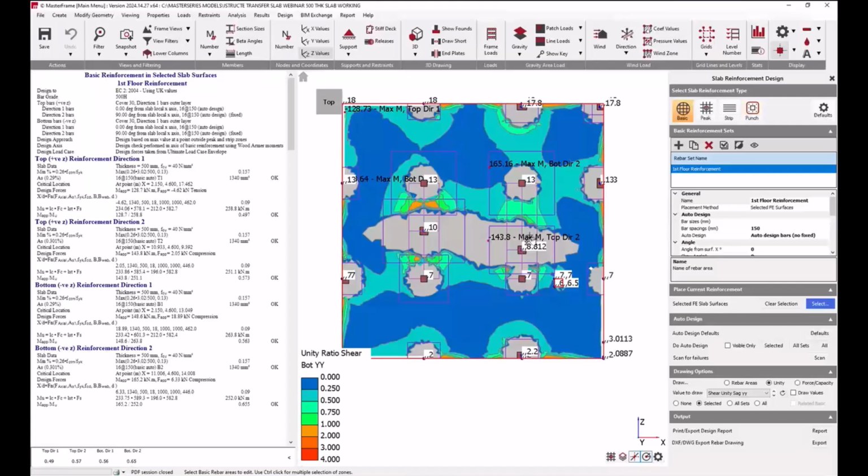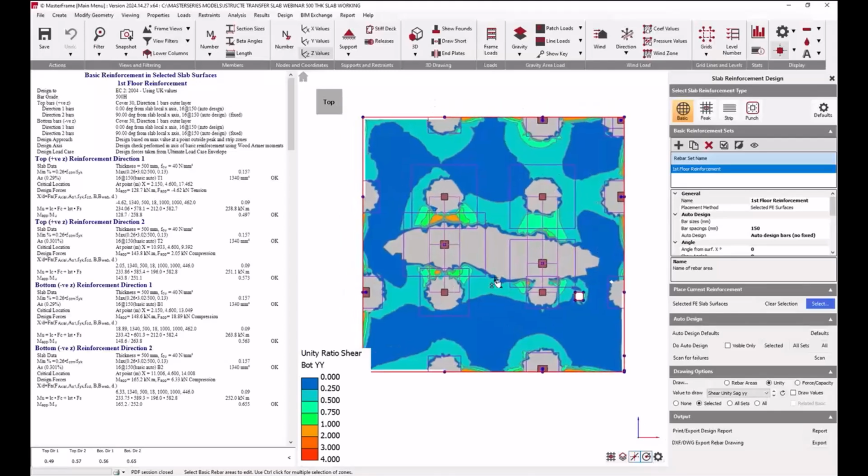Even though we see failures occurring, this is the unshear reinforced capacity where we need to do more detailed shear checks. So that'll identify the regions that we need to zone in on, so you get a clear indication from your contour plots where we should focus our attention. So this shouldn't be used as an indication of final design failure, as no support face enhancement is considered, and it excludes the zones inside the U1 or 2D punching shear perimeters setup.